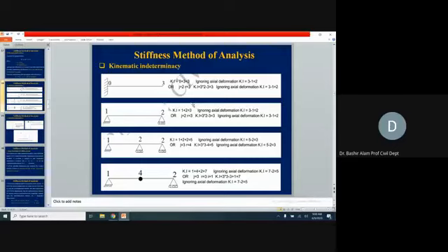at the right we have a roller support. It is a simple beam condition, a simply supported beam condition. Now, at the left support, we have 1 degree of freedom, which is rotation here. The beam is going to rotate this way. So we will be having only this rotation here as unknown. So that's why 1 is written here.